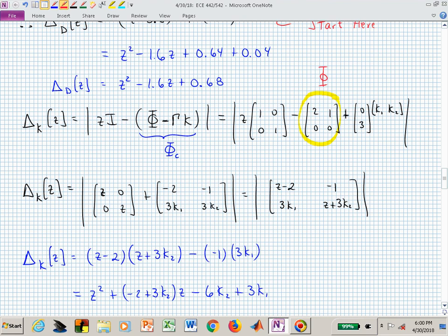In this case, our linear coefficient, the coefficient that is scaling z to the 1, only contains one of those full state feedback gain component values. So now we have one equation and one unknown, and we can solve these two equations and two unknowns in a sequential fashion and make the analysis a little easier, and not have to do two simultaneous equations to find those two unknowns.